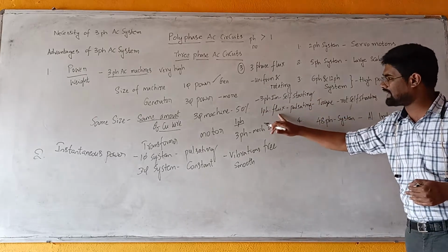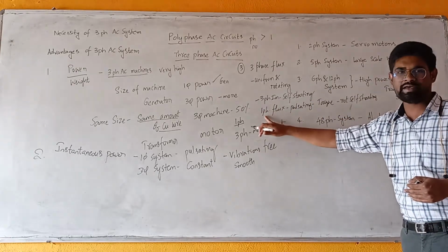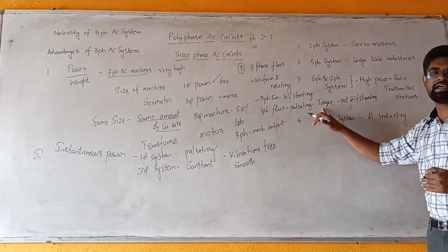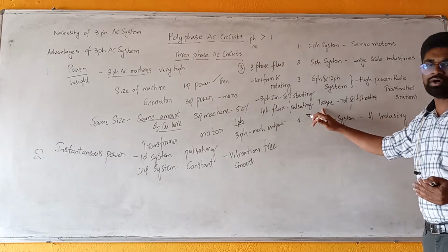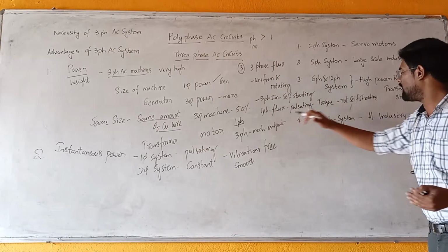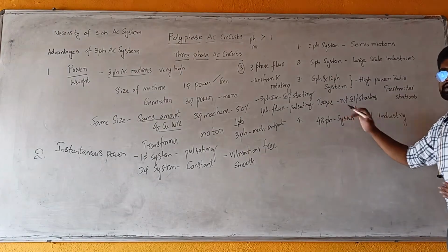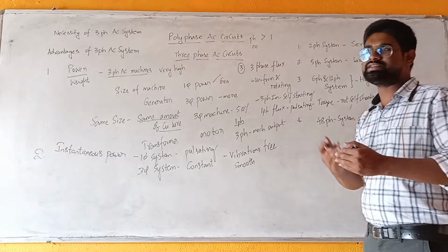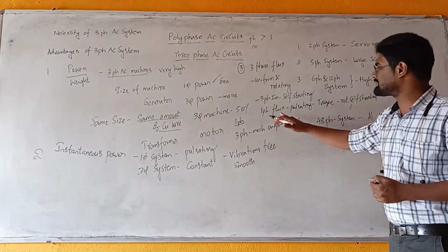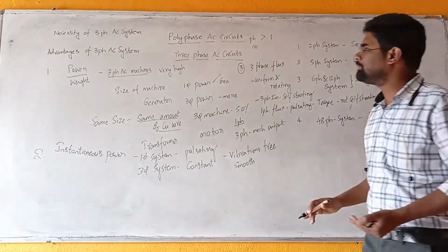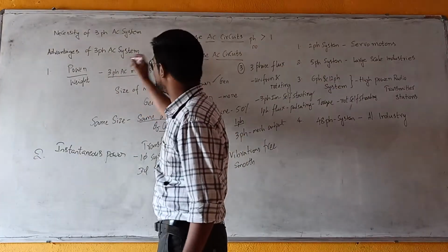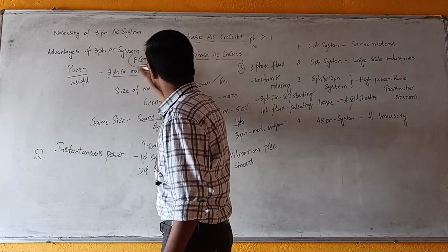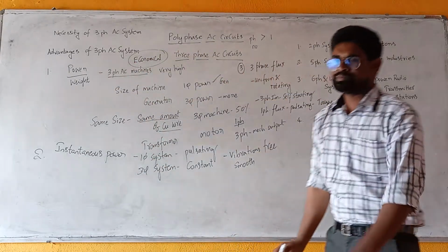Whereas if you consider flux which is produced from single phase AC supply, the nature is pulsating, so a pulsating torque is produced, and the induction motors for single phase supply are not self-starting motors. We have to do additional arrangements, which means that it increases the cost. So single phase system is not economical. From the first point also we can write a conclusion like: the economical system is the three phase AC system.